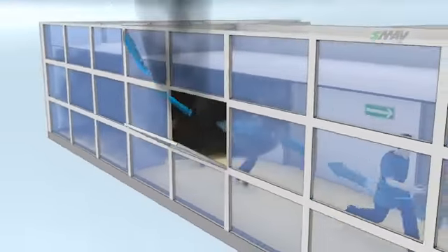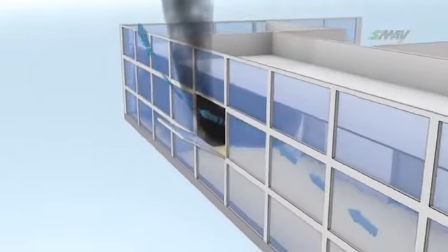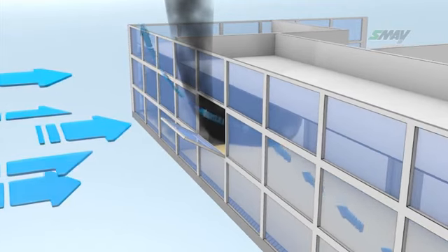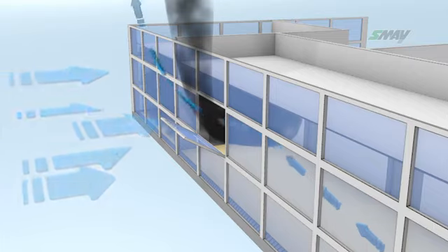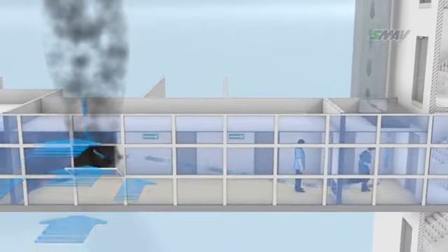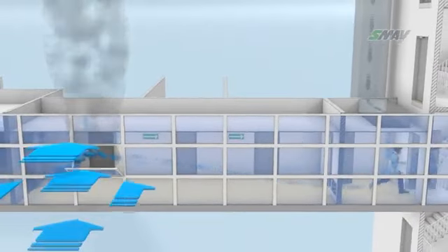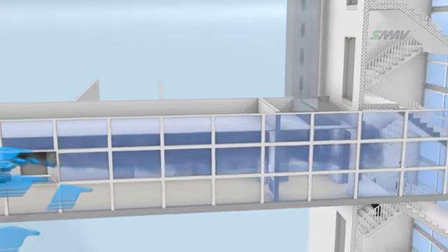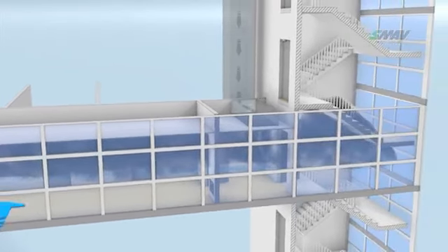The detrimental effects of external factors should be taken into consideration if using natural ventilation. For example, strong wind blowing at right angles to the facade with the window may cause a zone of overpressure which will, if the doors between the corridor and the stairwell are opened, prevent effective extraction of the air and smoke mixture. As the air and smoke is not being extracted, it may flow into the stairwell.